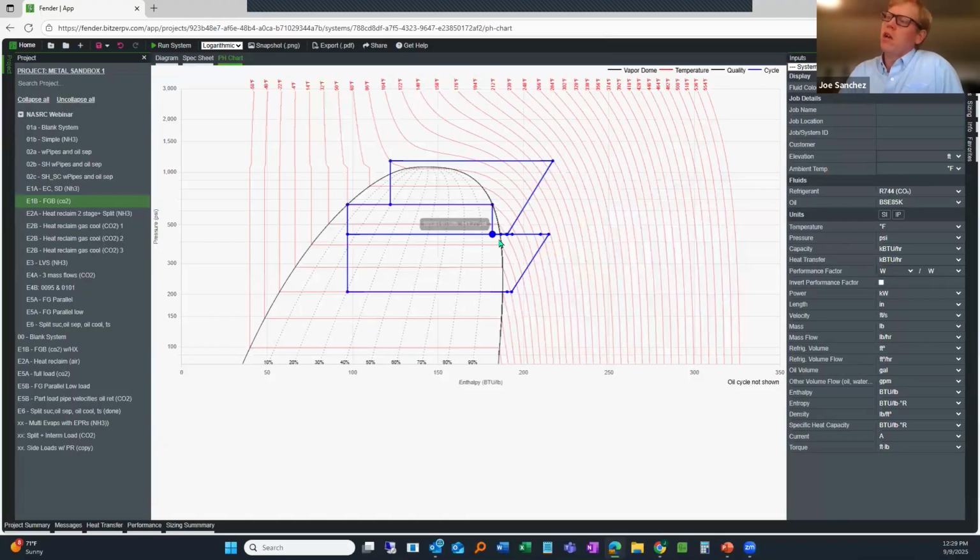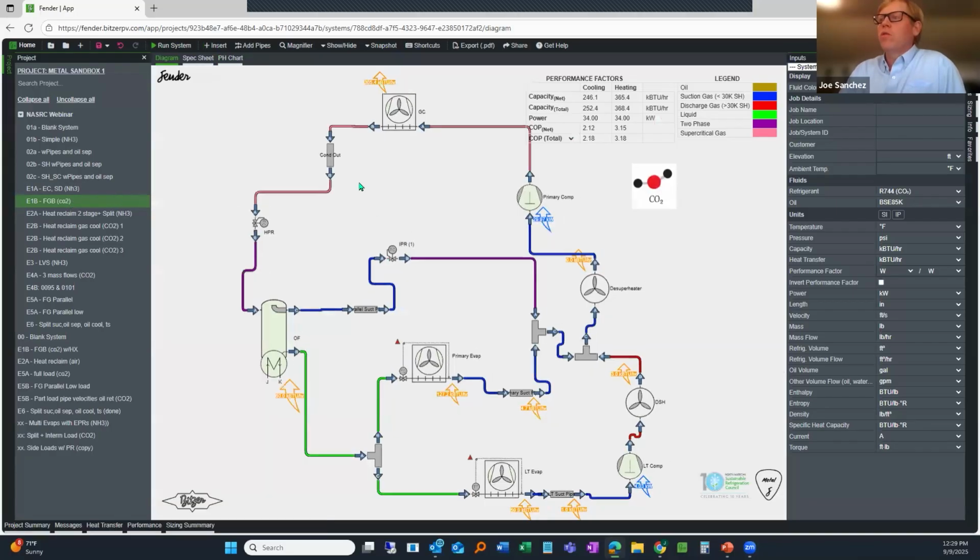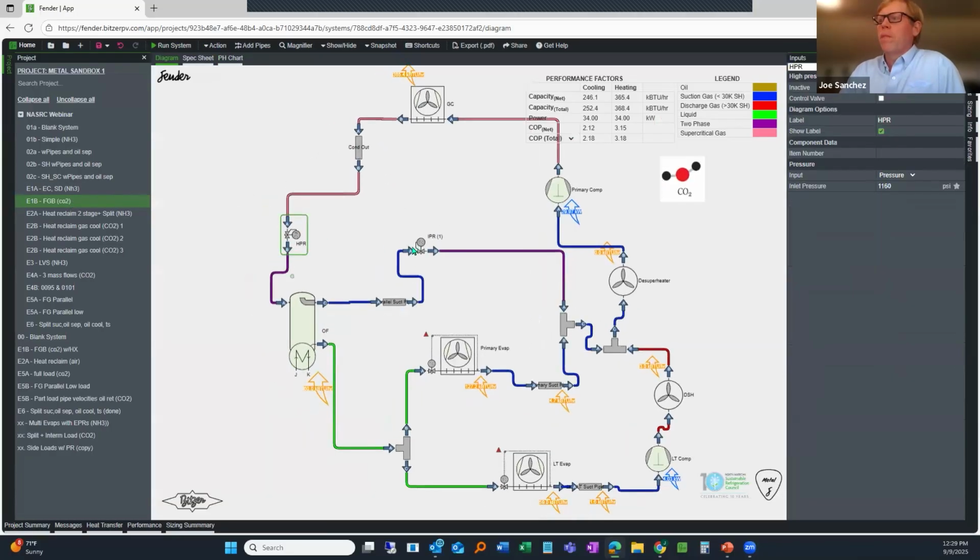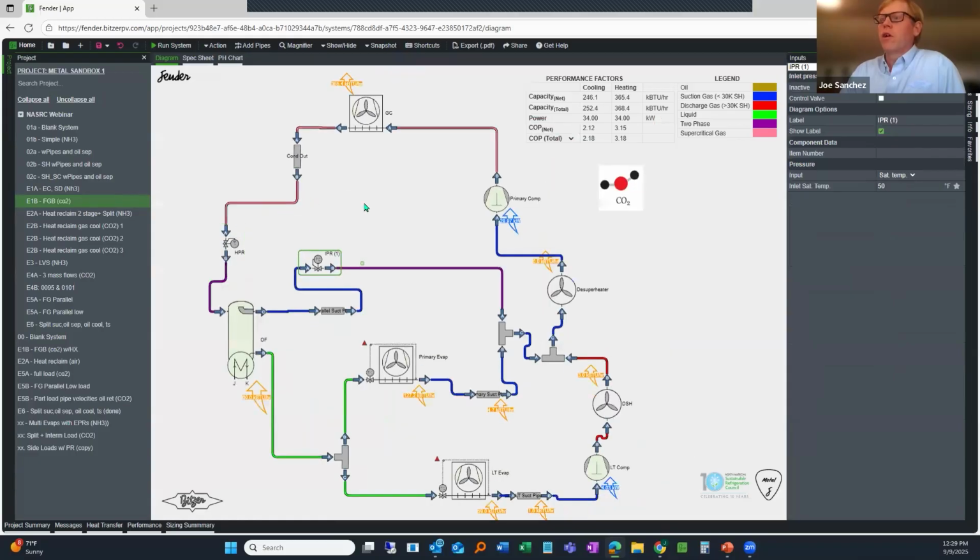You can see with CO2 we're operating much higher in the vapor dome, and so when we expand, we're actually getting wet, about 5% wet. So not a lot, but it's still enough that it could do damage to components that we don't want to have liquid. So this is why you'll almost always see these two lines married together with a heat exchanger.